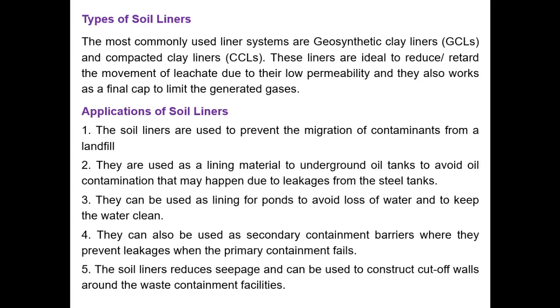Types of soil liners. The most commonly used liner systems are geosynthetic clay liners and compacted clay liners. These liners are ideal to reduce or retard the movement of leachate due to their low permeability, and they also work as a final cap to limit the generated gases.